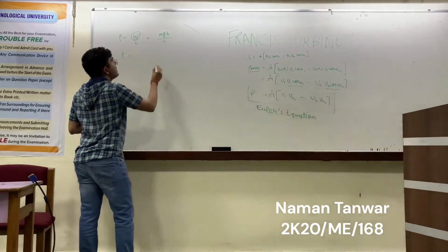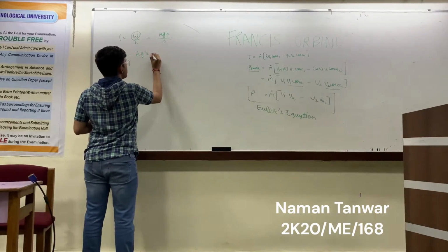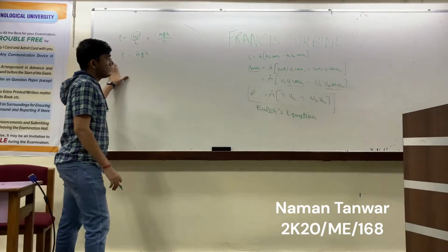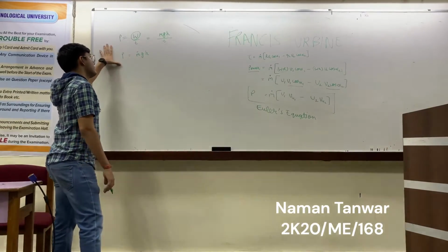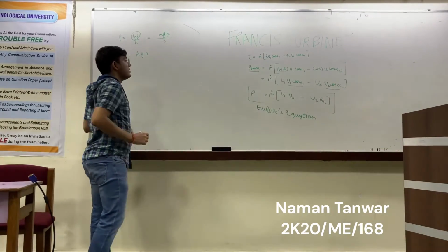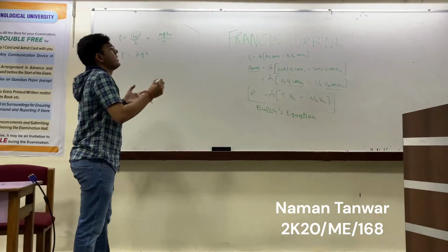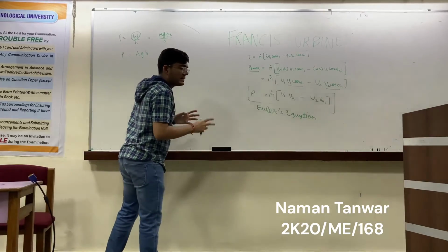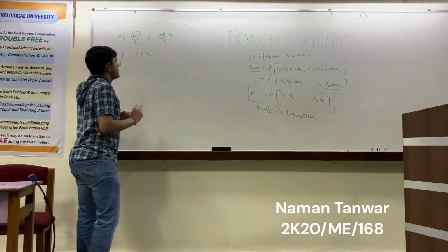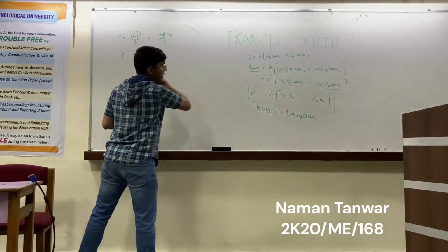We can rewrite m upon t as m dot gh. Also, when we are finding the power generated by the torque, we are taking an ideal case, so the height which we are taking will be the ideal one. Let's call it Euler height, because we are manipulating this equation only. So let's call it HE. We can now equate these equations.